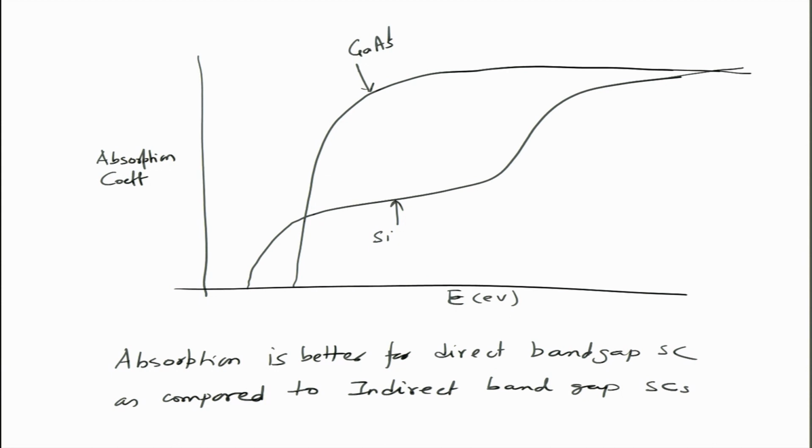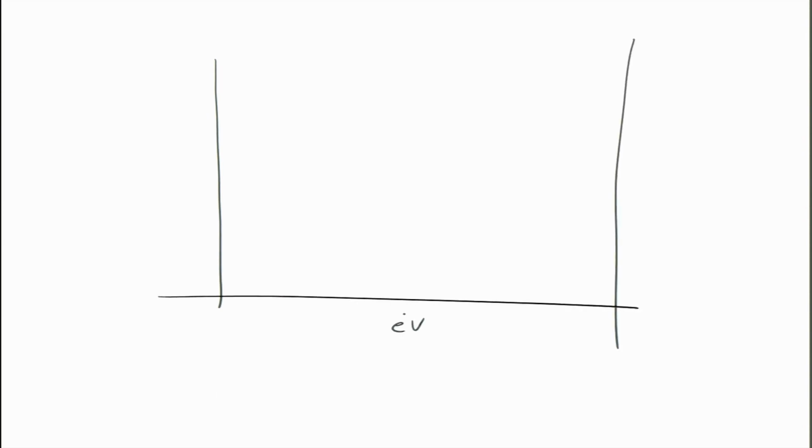And if you just plot the efficiencies as a function of band gap, this is what we have right now. So, I made the plot of eV versus eta, it was something like that, okay, and this shows a maximum at around 1.3, 1.4 electron volt. Let us say this is from 0.5 to 2.5. This is for single junction devices at about 33%.